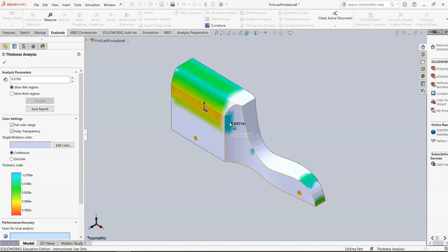This right here is actually the thickness in front of the chamber. So if you look at it from the bottom, the chamber kind of pushes up into here, and that area right there doesn't necessarily need to be greater than 0.375. I usually keep that greater than 0.1 in that area. This is the area over top of the axle. No worries there. And coming to a point here, you're always going to have a little bit of color there too. So even though this has a lot of color on it, none of it's bad.